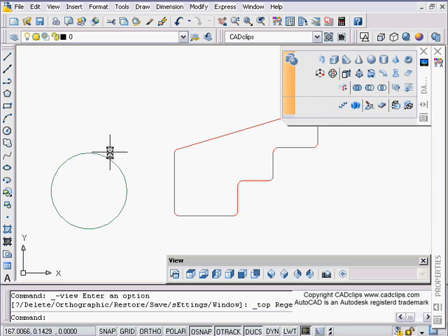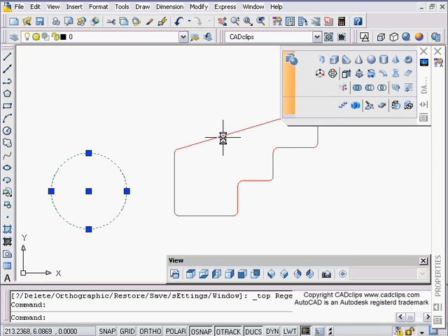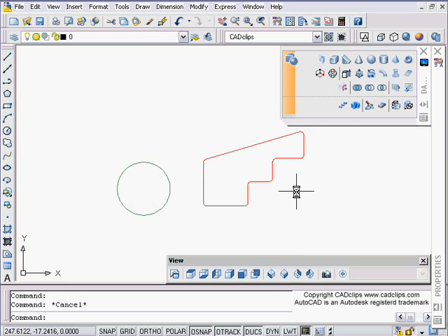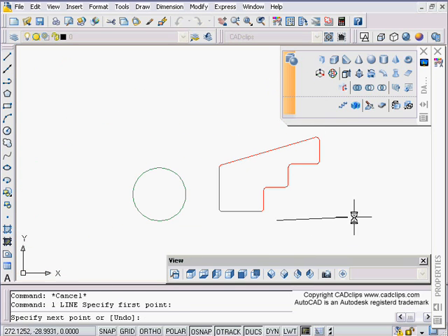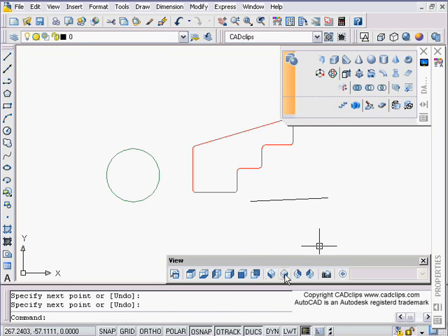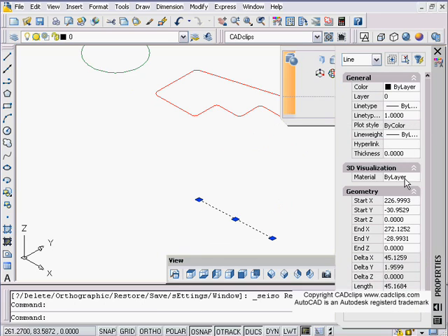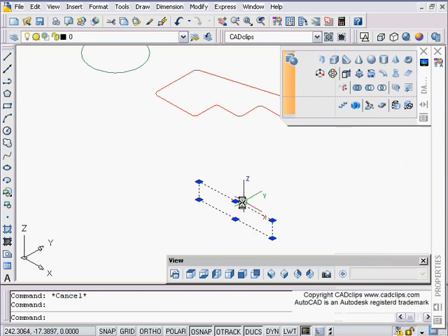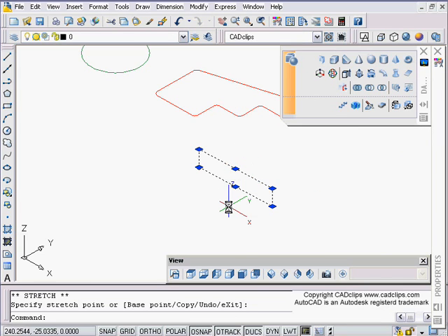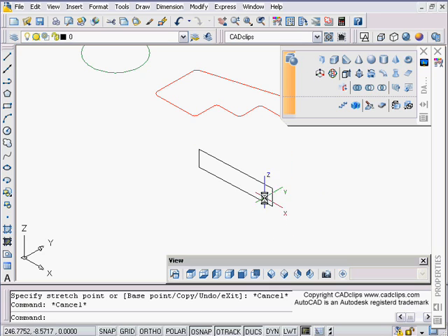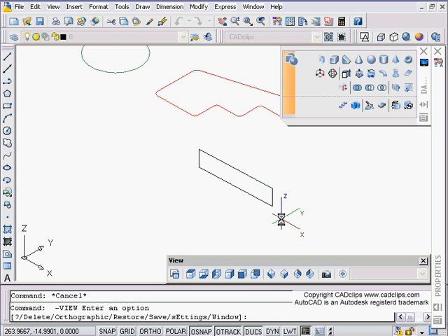And what I'm talking about with thickness, here I just have a circle that's got some color. This is a closed polyline that has filleted corners, and I can even just draw a line over here. It doesn't matter. Go look at that in 3D. Any object can be given thickness. If a line is given thickness, it just kind of springs up from there. After that you can move it around, but it's a line that has vertical thickness, so it goes up in the Z direction.